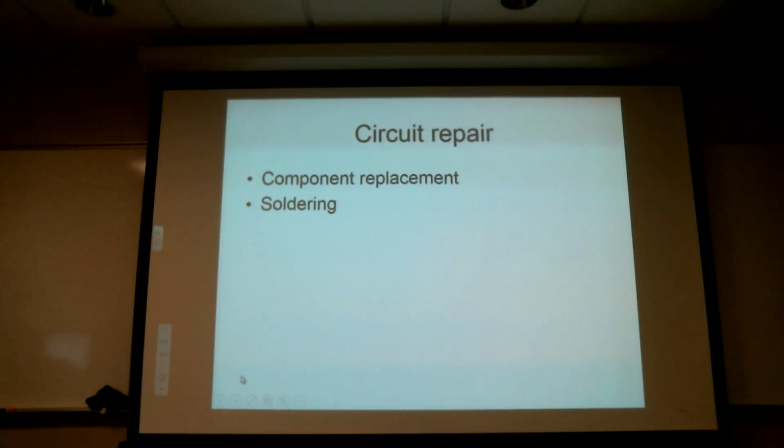Circuit breakers, section. Remember we talked about derating switches and derating some components because of, what did we call that? What was it that caused derating to be necessary? The inrush current. Remember we turn on a light, current's really high until the filament gets really hot, the resistance goes up. Same thing with an electric motor, turn the current on, there's no counter electromotive force till it comes up to some speed. Okay. Switches.